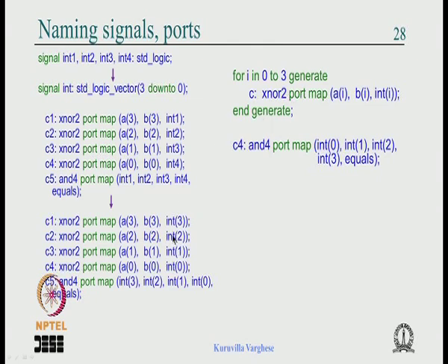So whenever there is symmetry, you think of defining the signal properly, writing the instantiation properly so that this can work out. It's not that you need to write it one way and then rewrite it another way, but when you put it down, you see the trend and you can write it, and you can write a ripple adder as an example. And this can work not only for component instantiation. If you have a full adder, you can write the equation for the full adder, and that can be in a generate loop that will be replicated.